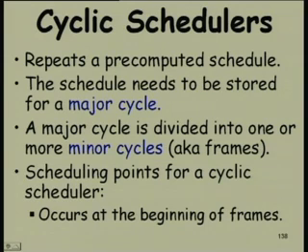We also store a schedule here, but we divide it into two parts, the major cycle and the minor cycle. The schedule repeats in the major cycle, and each major cycle is divided into minor cycles, which we will call frames.